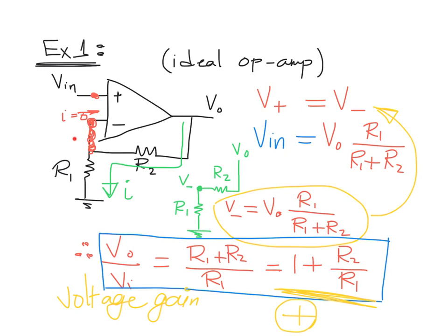Right now we have the other equation regarding the current. The current going through this branch in the red line will be 0, and from the other side, if Vin is connected to anything else, the current flowing through this branch will also equal 0.